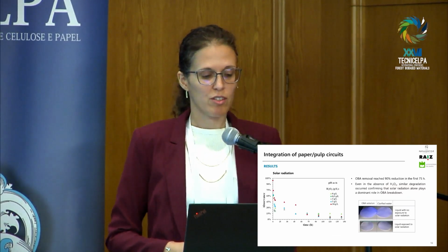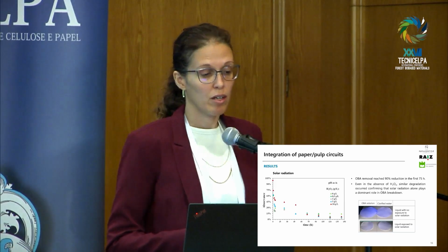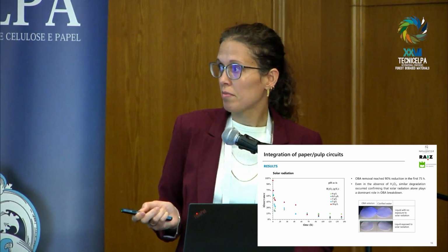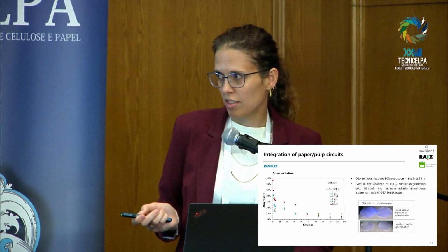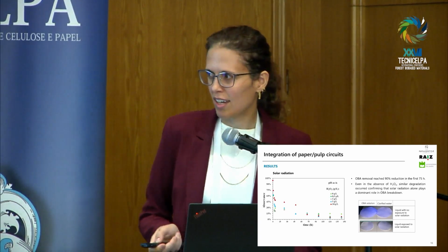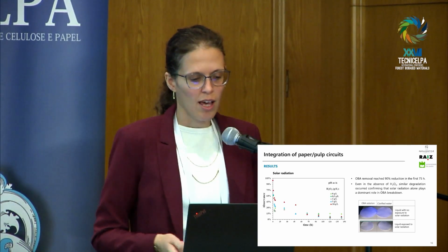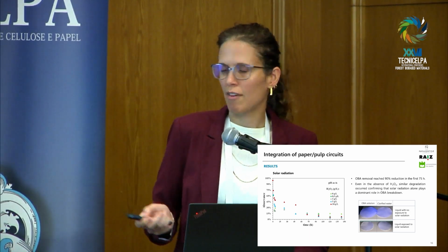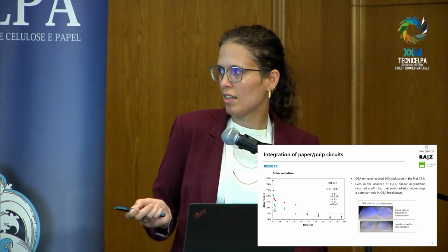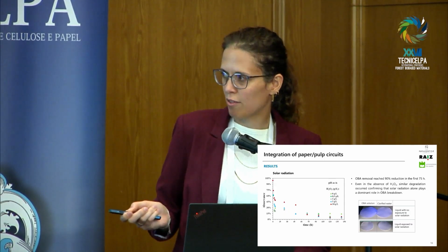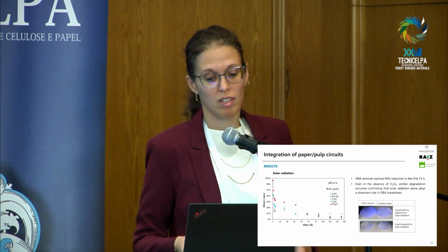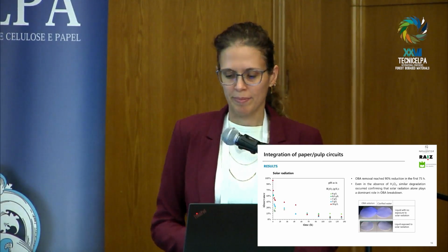By exposing these solutions to the sun, the OBA, by checking the absorbance, seems to be removed effectively, but we are talking about 75 to 90 hours, so not a very adequate time for an industrial process. Anyway, with these solutions obtained after exposing them to the sun, we did some pulp sheets to check if this decrease in the absorbance resulted in decrease in the fluorescence in the pulp. And yes, compared to the liquids that were not exposed to the sun, the differences are visible.